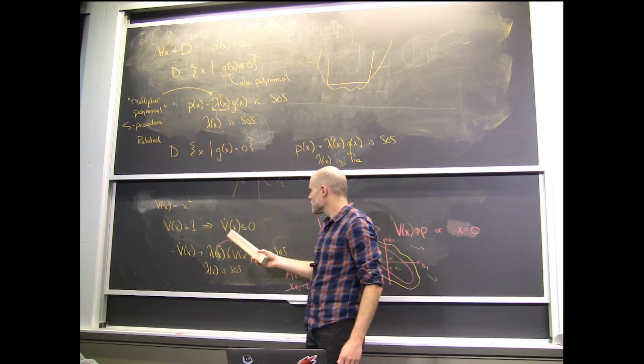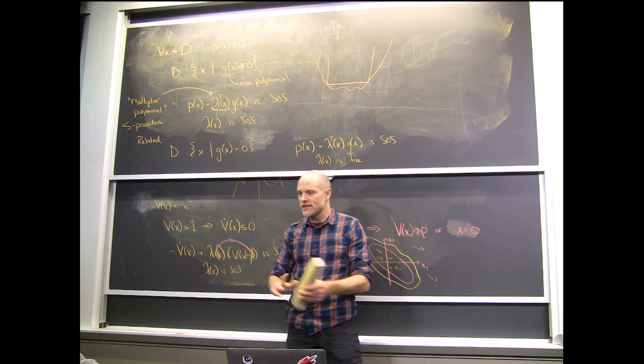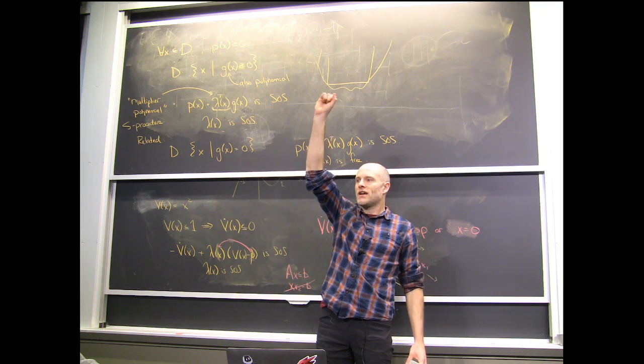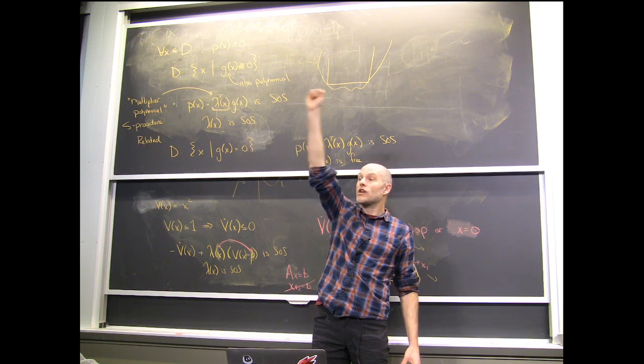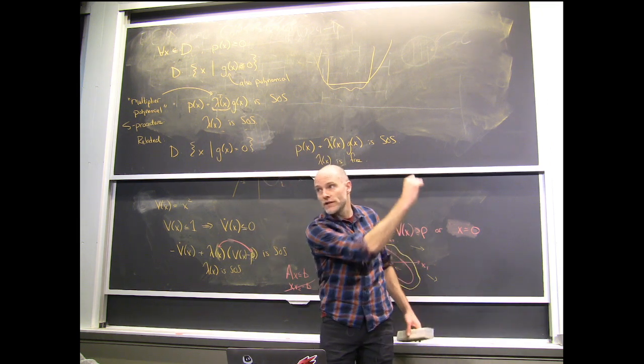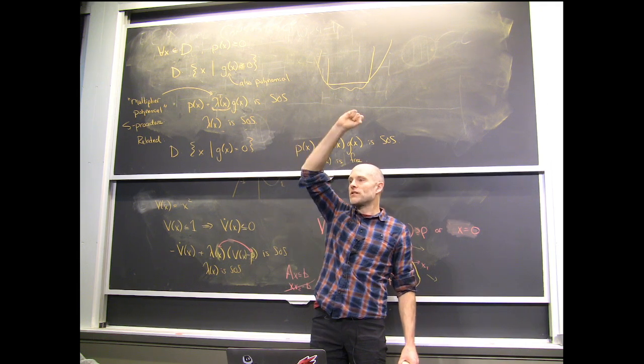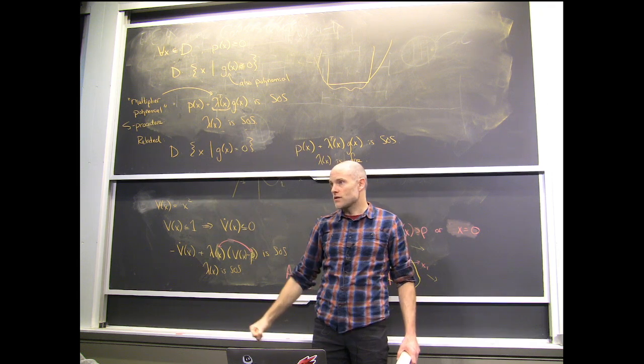So you said V dot of x. What I'm worried about is for a system, let's take the example of balancing an acrobot at the top. I compute an LQR controller. I know it's going to work around the linearization, but if it gets too far, it's going to fall down. So asking for that cost to go to be a Lyapunov function globally is not going to work.